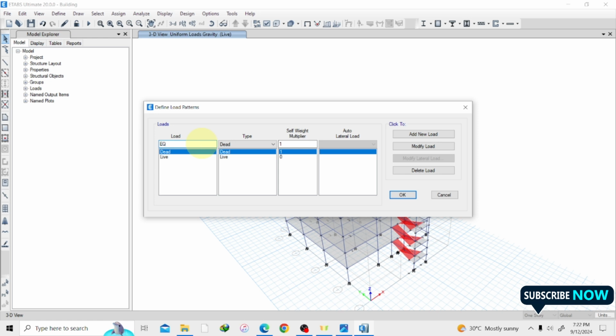So EQX, let's represent this like earthquake in the x direction. So that's the name we are going to give for the seismic load in the x direction. And the type of the load, we are going to click here and just scroll down. You will see seismic. So it is this seismic we are talking about, not seismic drift. So seismic and the self-weight multiplier, you don't have to change anything, it's already inputted into the app.